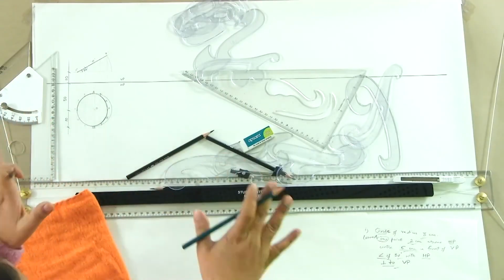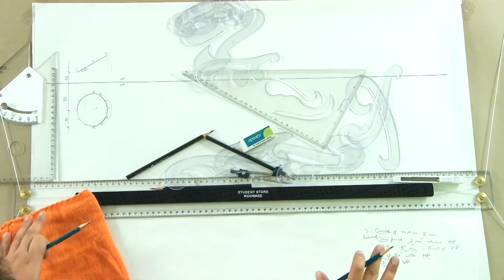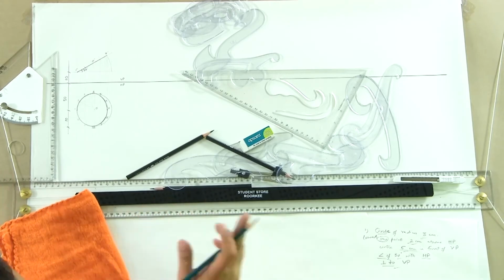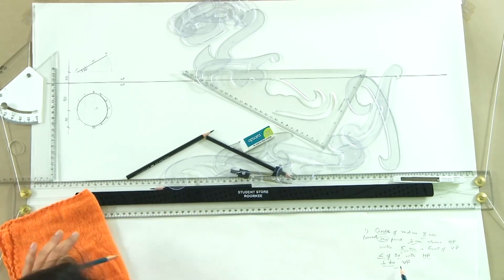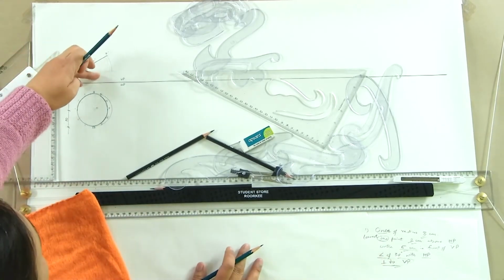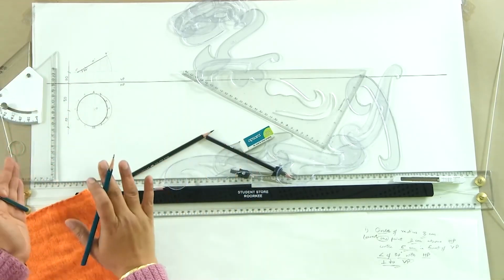These are the steps. You will start by assuming that the plane is parallel to one of the reference planes and then gradually inclining it. To start with, you should keep the plane to which it is perpendicular as the same. In this case, it was perpendicular to VP. We took it as that, and then we inclined it with HP.